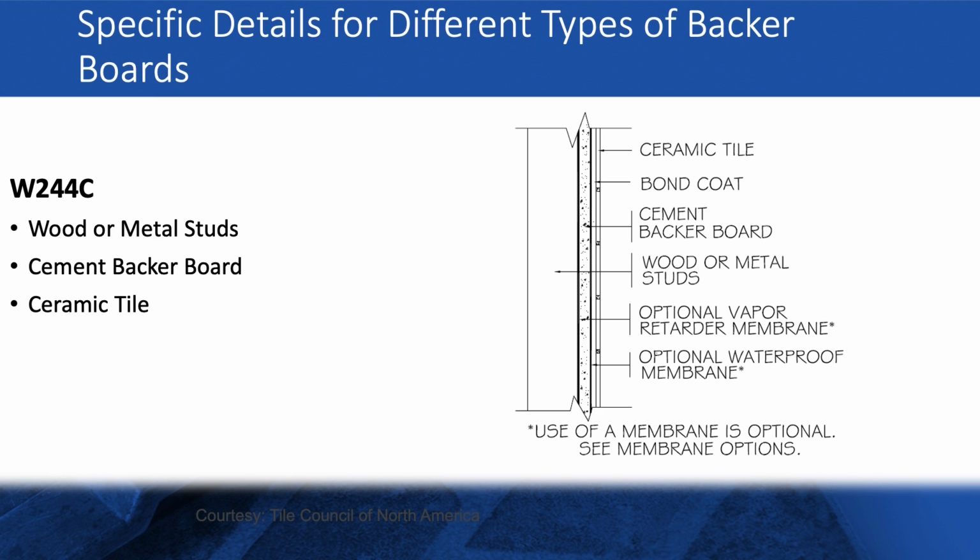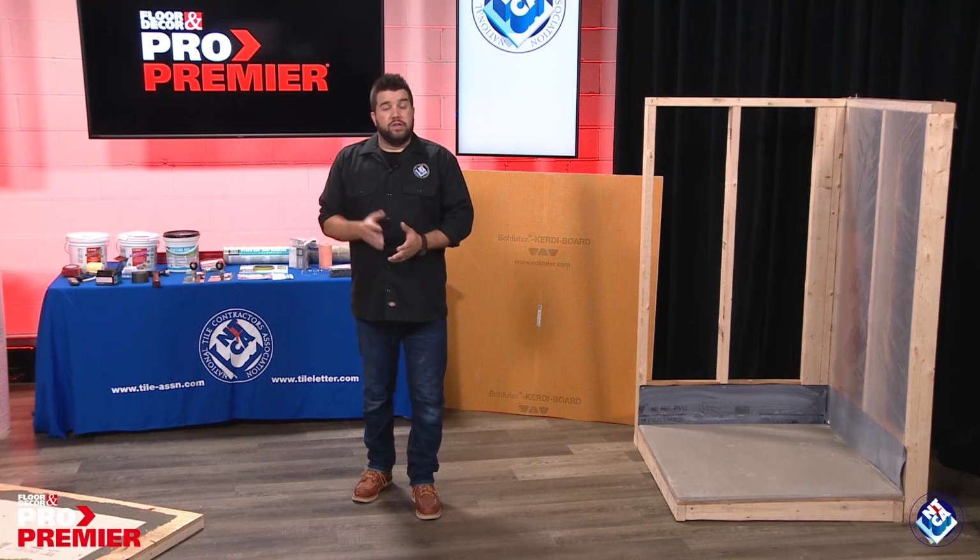At inside corners, we want to allow for an expansion space between the sheets on an adjacent wall. Tape the joints with a skim coat of latex Portland cement mortar, but do not allow the mortar to fill the open space between the backer board sheets. This board may be used in areas exposed to temperatures exceeding 125 degrees Fahrenheit. This is also important.